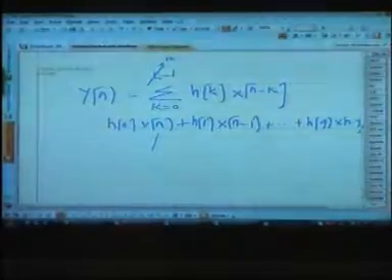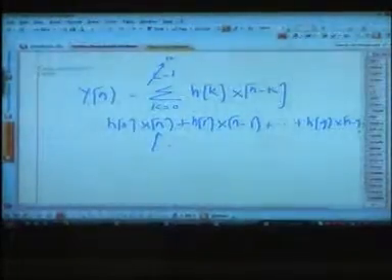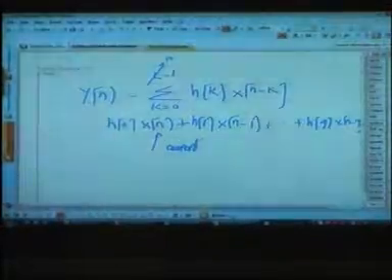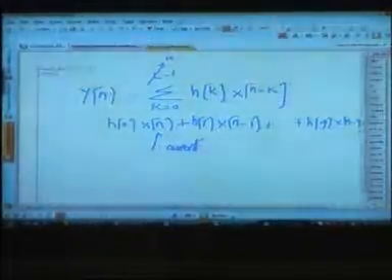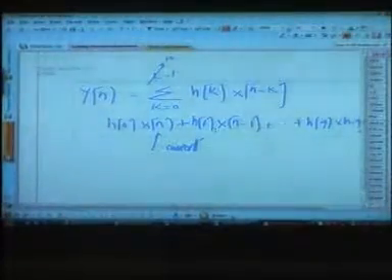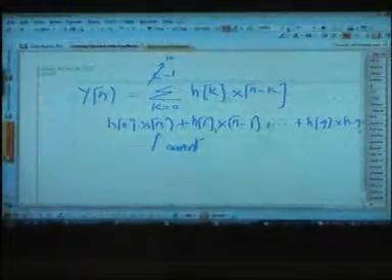From a signal processing perspective, xn is the current sample, the most recent sample you receive in your stream of data. It tells you that you require the current and the 9 old samples to implement this algorithm.